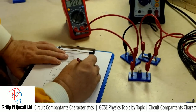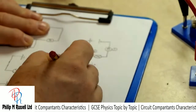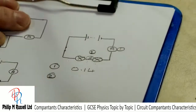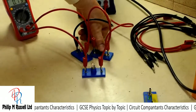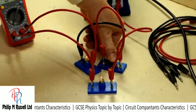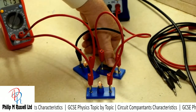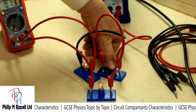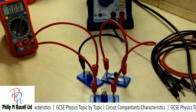This time I'm placing my ammeter between the two bulbs. I'm going to label it position number 2, and we'll see what happens. And I have got a slight change here, 0.13. I wasn't expecting that.